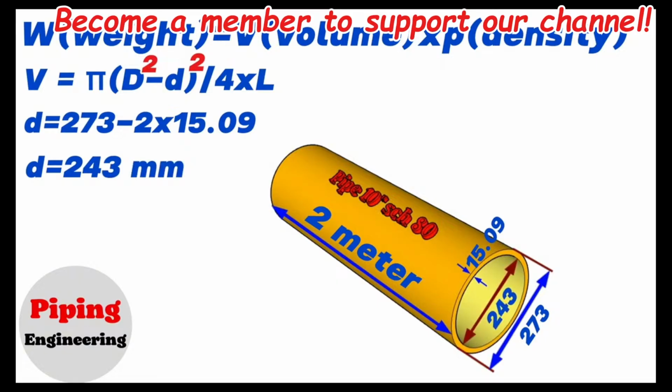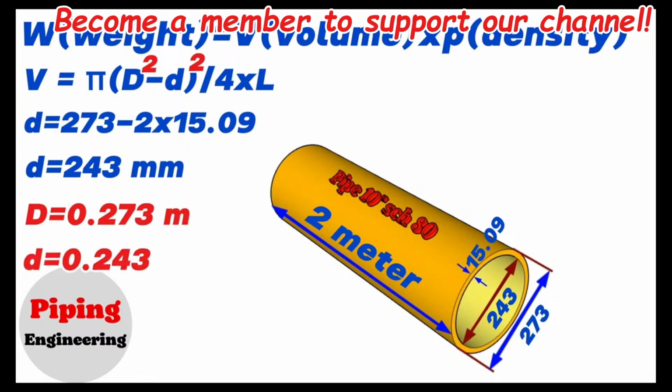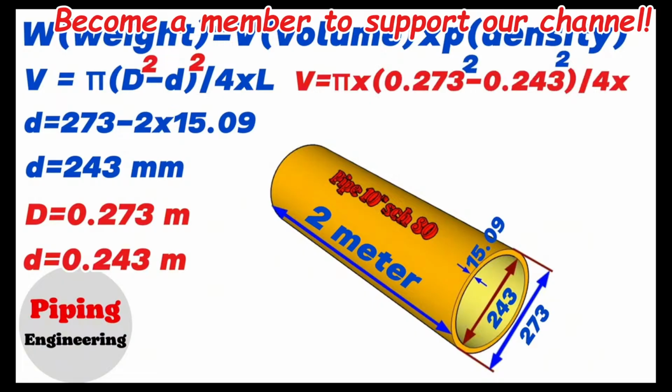These dimensions should be converted to meters, because in the density charts of ferrous metals they use meters. Then, the outside diameter of the 10-inch pipe in our example is 0.273 meters and the inside diameter is 0.243 meters. We also know that the length of the pipe is 2 meters. Now let's write this information in the volume calculation formula. The volume of the 10-inch pipe equals pi multiplied by, in brackets, 0.273 squared minus 0.243 squared, divided by 4, multiplied by 2 meters.